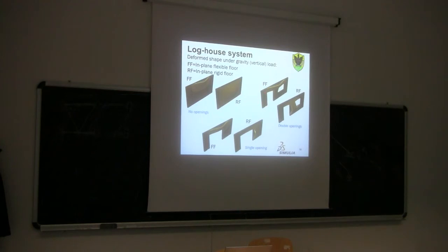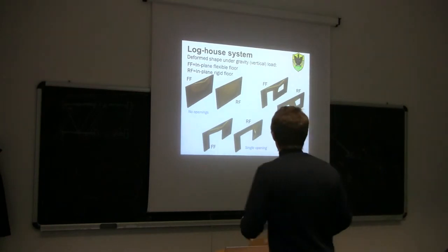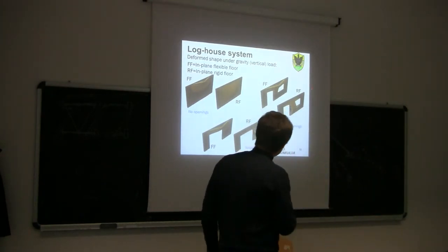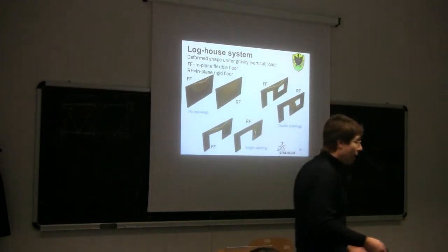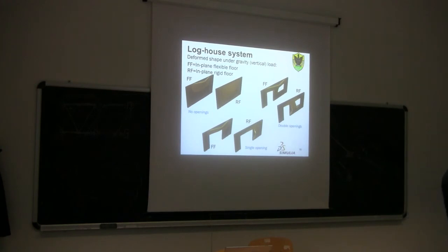So here, as you can see, we don't have a problem of buckling, but here in between we may have a very serious problem of buckling, because here we don't have any perpendicular wall providing some restraint. So particularly this part between the door and the wall, out-of-plane flexural buckling is a serious problem. How to reduce this problem of flexural buckling?